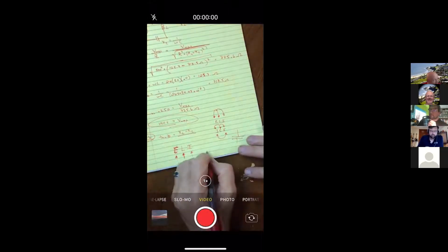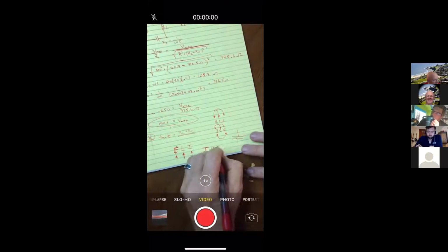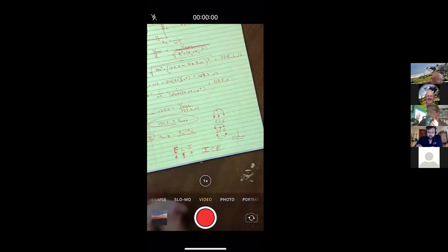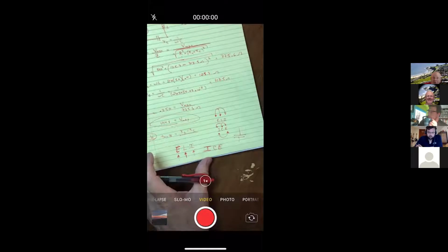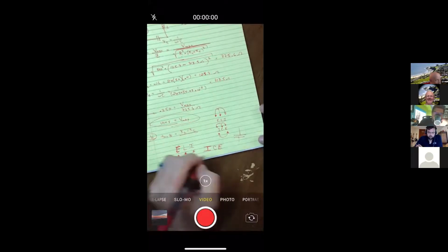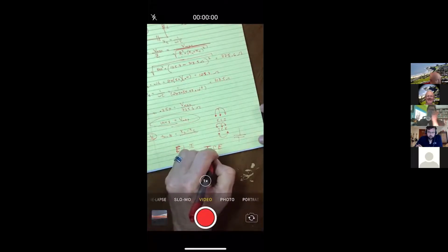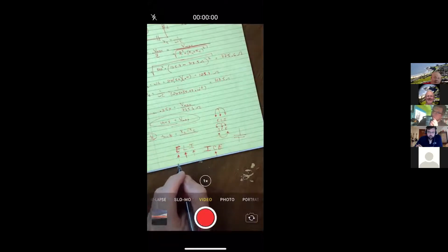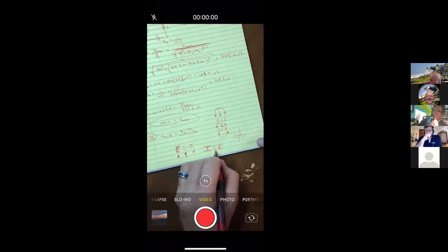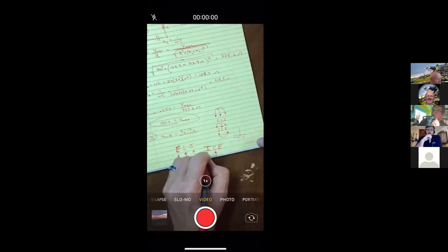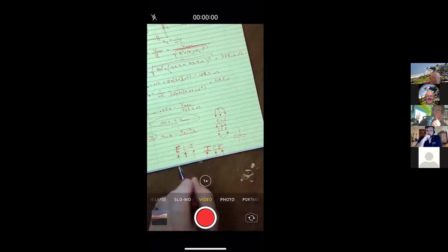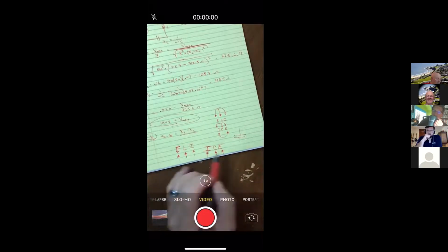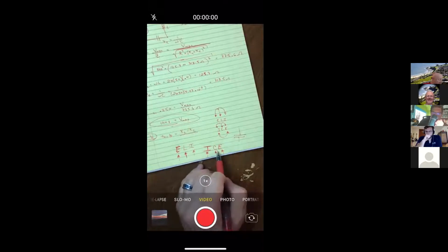And I'll say the same thing for ICE. I'll write out the word ICE again. It's a nice way to try to remember which comes first, the current or the voltage, that is the EMF. And so imagine the middle letter, the C, representing, hey, this stands for a capacitor. And so in the capacitor, the first letter is the I. So that tells me current comes before the EMF, before the voltage. So you get current before the voltage in a capacitor. I know it's a capacitor because it's C.